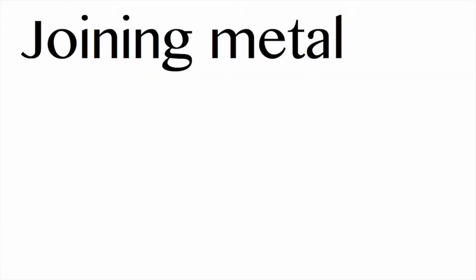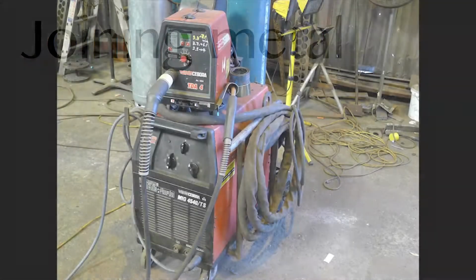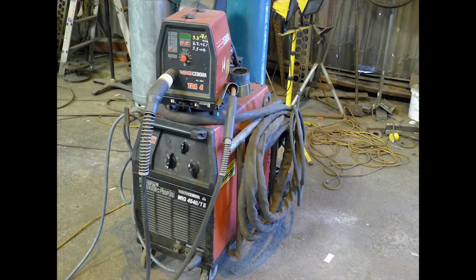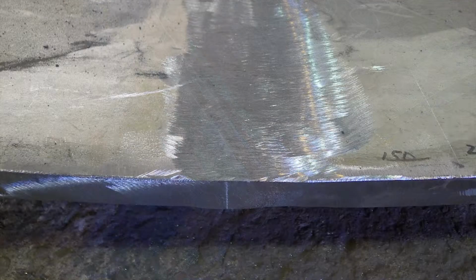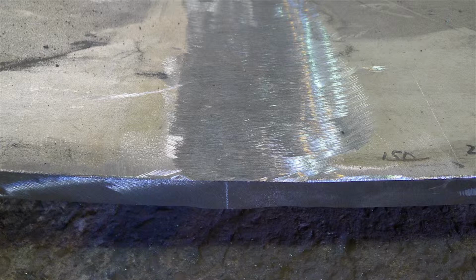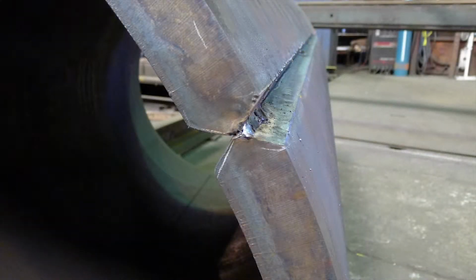ER Curtin uses gas metal arc welding and submerged arc welding as their main metal joining processes, in many ways similar to schools, but on a larger scale. The welding machines are connected to a 3-phase 550 volt supply, which is more than standard 3-phase at 415 volts. This allows for higher capacity machines to be used and much longer duty cycles.